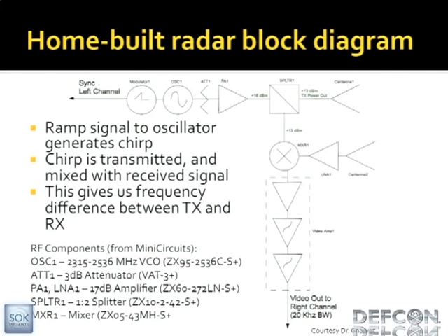and that's what I said before was the local oscillator for that mixer. So then what happens is the signal gets sent out by one antenna, it gets reflected off of whatever, and then it comes back and the other antenna gets amplified again because it's going to be really, really weak now. Remember that 1 over r to the 4th thing I was talking about? And then it gets mixed with that known signal. So basically, what we did is we took the signal and we shifted it all the way down to pretty low frequency near DC where we could record it.